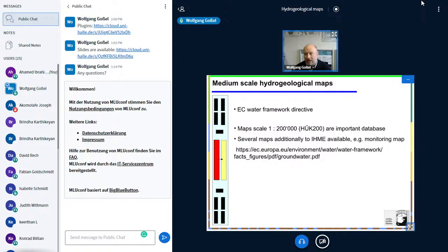In general, you can say we are by now, at least in the federal states which are spatially big, at a resolution of one groundwater observation well for each square kilometer at least. Or in some parts, of course, you have some tens of them per square kilometer, especially in Berlin. On their 880 square kilometers, they have around about, what was the number, 2,500, out of which around about 1,500 are observed by the waterworks and 1,000 by the Senate. And yeah, you can calculate, of course.